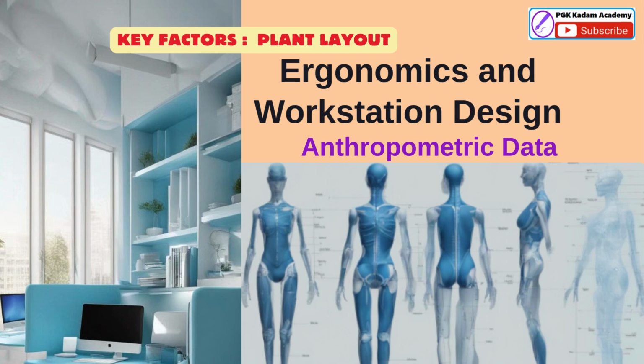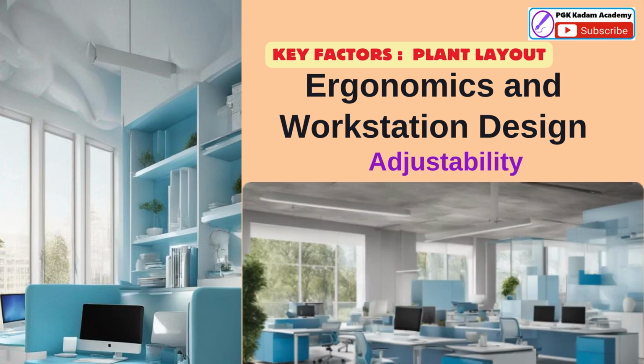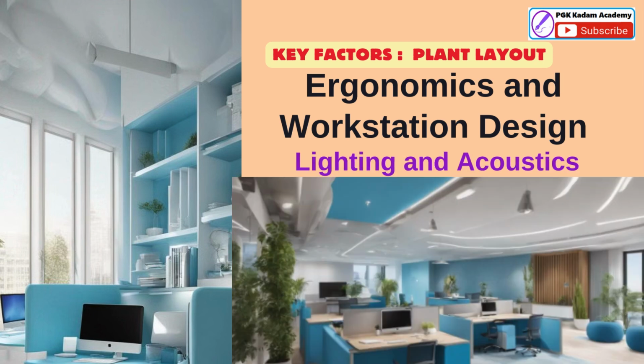Next factor is ergonomics and workstation design. Anthropometric data. Use human body measurements to design workstations that accommodate a range of worker sizes and capabilities. Task analysis. Analyze specific job tasks to optimize workstation layout and reduce physical strain on employees. Adjustability. Implement adjustable workstations and equipment to accommodate different workers and tasks. Lighting and acoustics. Ensure proper lighting and noise control to create a comfortable and productive work environment.